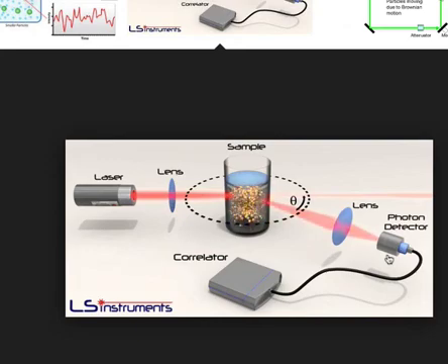The clever piece in the dynamic scattering is that there is a slight delay in between a few of the pulses, and that allows for the particles to move slightly due to, I've forgotten the word, Brownian motion. A large particle won't move very much, a smaller particle will move more, and at the lower level of our particle size distribution, this allows us to extend that range slightly by knowing the temperature of the fluid and doing this Doppler type of change of frequency because the particles have moved.